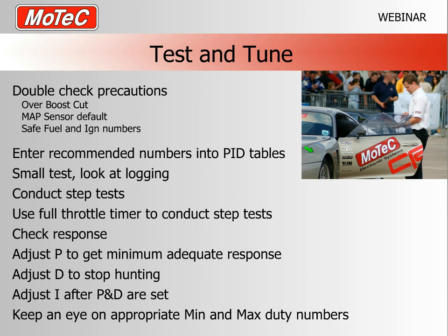You go out there and test. It's the only way of finding out. Double check your precautions. Check your overboost cut. Can't say this often enough, as you've already worked out. Map sensor default and safe fuel and ignition numbers. Enter the recommended numbers into the PID tables.